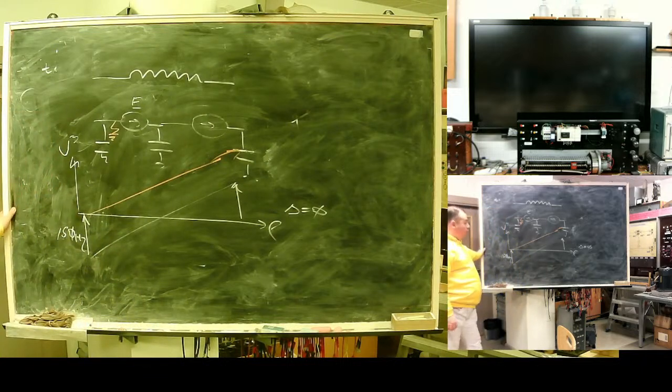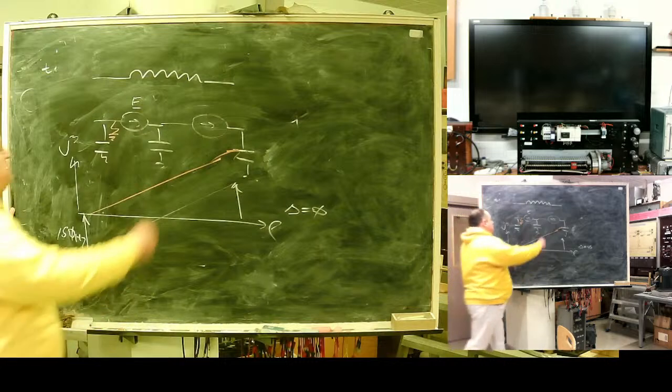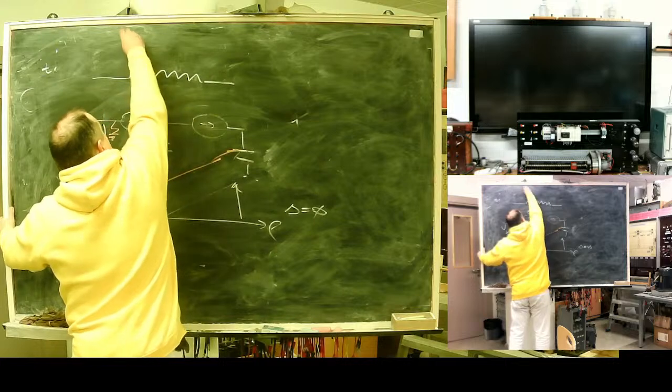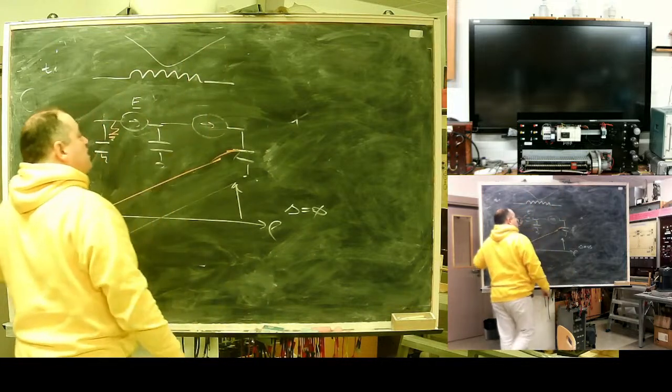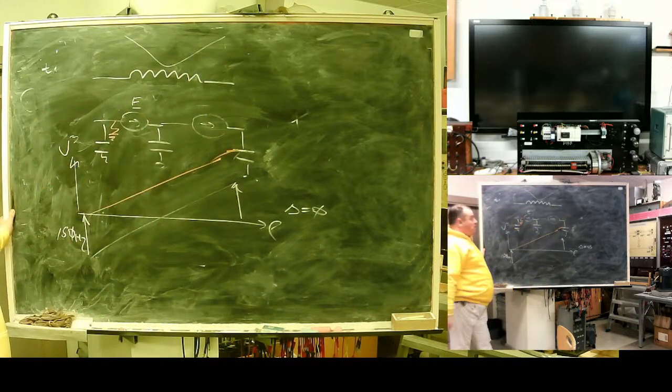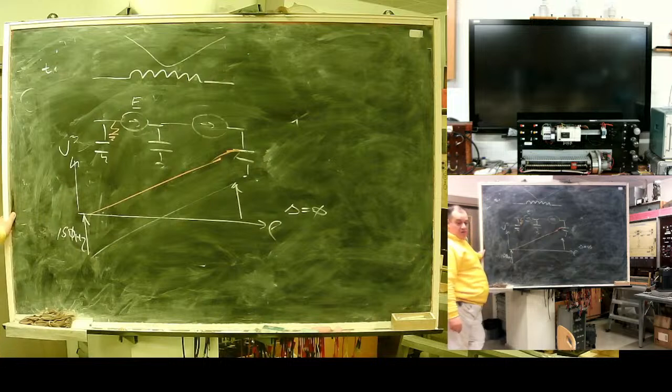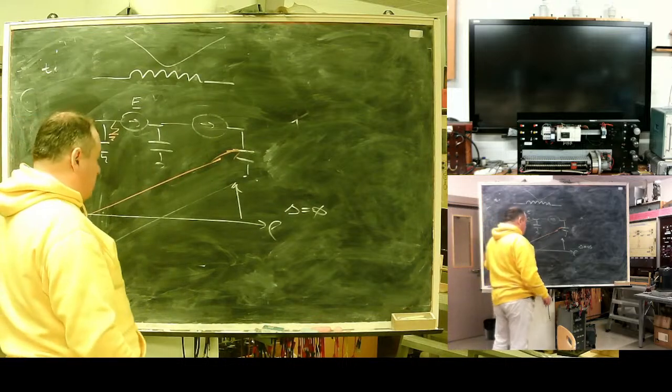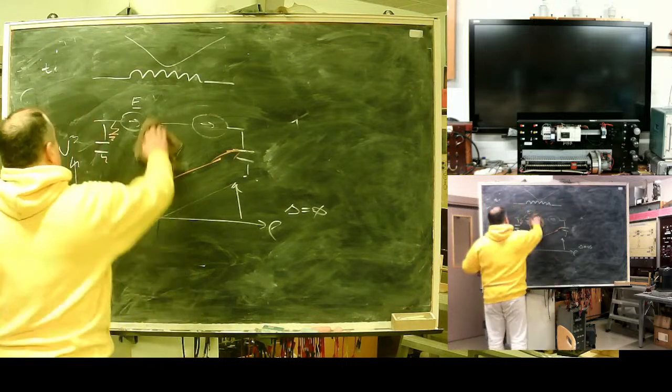Delta will be the full third harmonic voltage of our winding. This protection has a sensitivity chart like this. It's less sensitive in the middle and more sensitive at the ends of the winding. Combined with the neutral displacement relay, you will get full protection for your generator. It's a protection from internal earth fault.